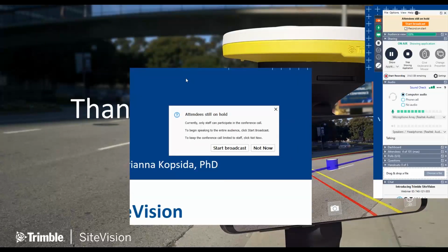So we're using an RTK receiver. So the general accuracy is typical RTK. So I will say a few centimeters, 2, 3, 4 centimeters, depending on the environment you're operating in. Those of you who've been working with RTK know that this can vary slightly, but it's that type of accuracy. If you don't use it with the GNSS, you only use it with the cameras, it will be less accurate.